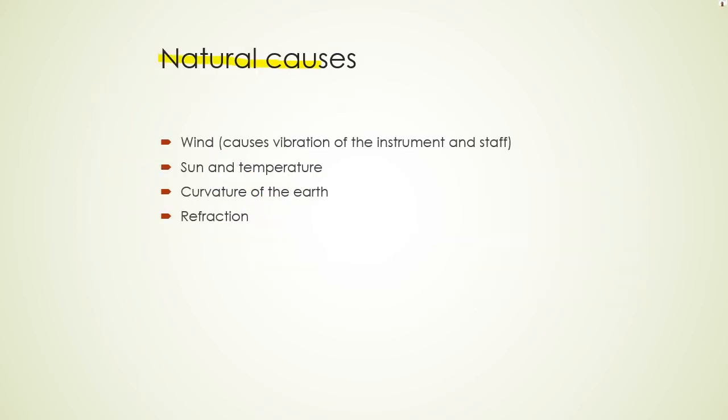The natural errors may be due to the wind, which will cause vibration of the instrument and staff. It may be due to the sun and temperature. It may be due to the curvature of the earth, and it may be due to refraction as well.